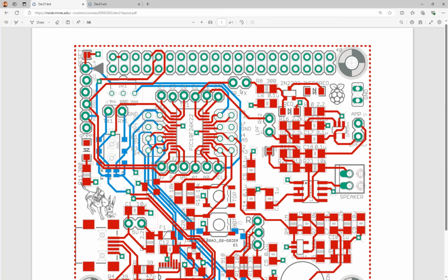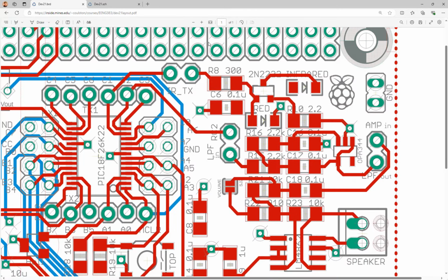So if I just want to probe the PWM, looking at this layout, see here is disconnected, right? You need a jumper on the top, okay? But now we don't have a jumper, for example. I don't put a jumper here. So in the lab, I program my PWM. I'm trying to create a series of pulses. I download it to the microcontroller. I just want to probe it. Do I need to connect it to the IR? I just need to look at the electrical signal, not the IR yet.